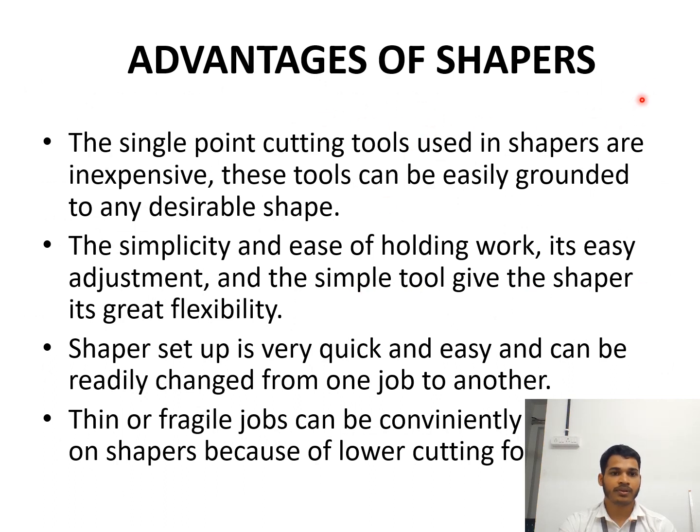Advantages of the shaper. The single point cutting tools used in the shaper are inexpensive. These tools can be easily ground to any desired shape, and the simplicity and ease of the work holding, its easy adjustment, and the simple tool give the shaper its great flexibility. Shaper setup is very quick and easy, and can be readily changed from one job to another. And thin or fragile jobs can be conveniently machined on shapers because of lower cutting force.